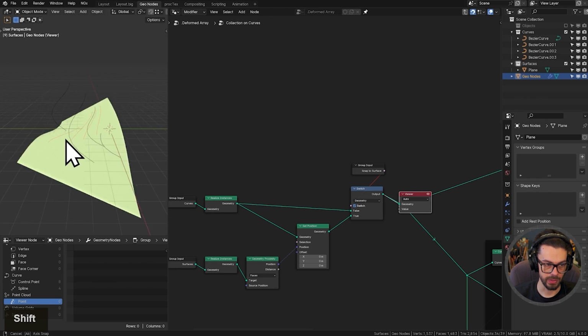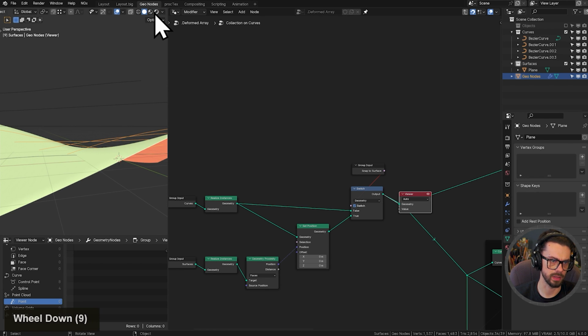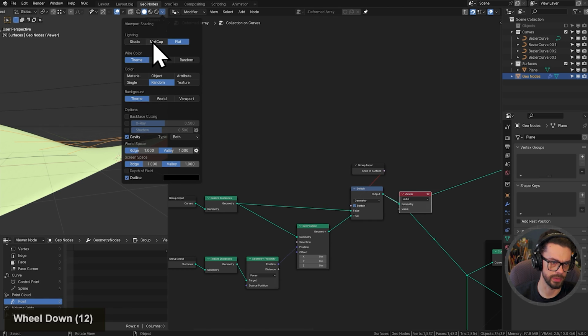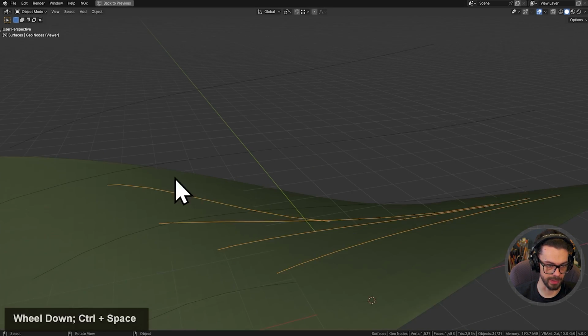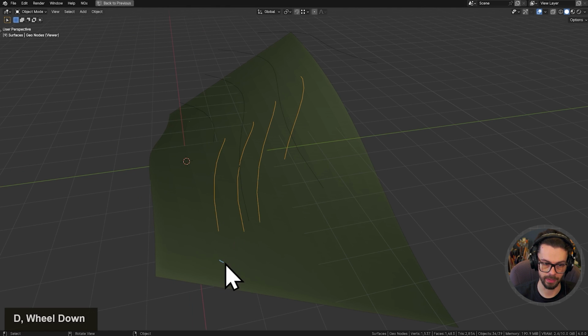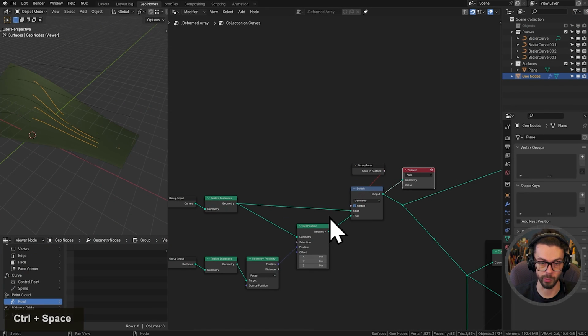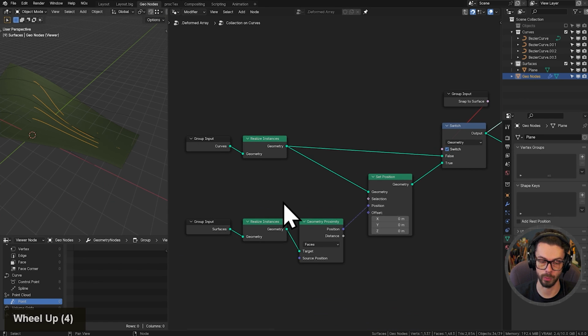That's really clear. So you can see our highlighted lines here, these orange ones, hopefully anyway. Let's go for a slightly darker surface color. So there we go. We can see that these curves have been snapped to the surface, technically. The positions that we can control on these curves, the control points, have been snapped to the surface. However, they're Beziers, which means that the rest of the curve has been sort of ignored. We've just positioned the control points.